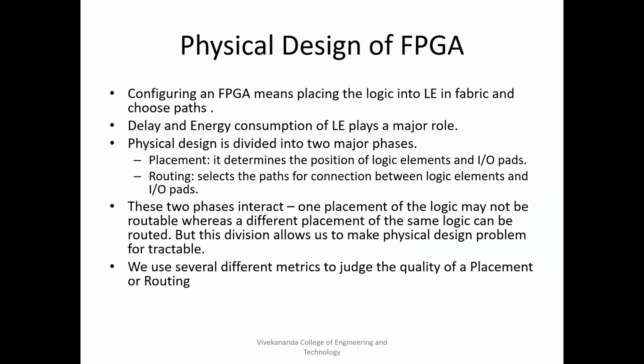Next is the design challenges or the physical design of FPGA. When we talk about physical design, we have already studied the FPGA architecture, what it has: a logic unit, a logical element, an IO block, input output block, and it has interconnects, how these blocks, various cells will be interconnected. Knowing all this, knowing what the components are, we have to place these components and we have to connect them. So placement and routing is a very important aspect in designing.